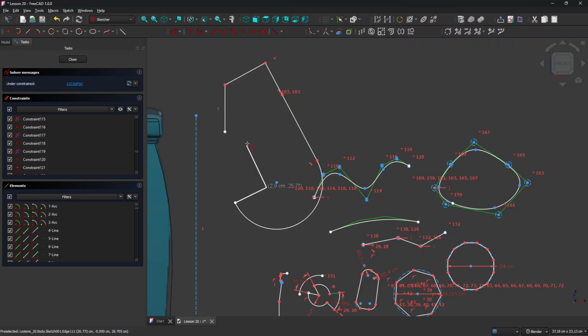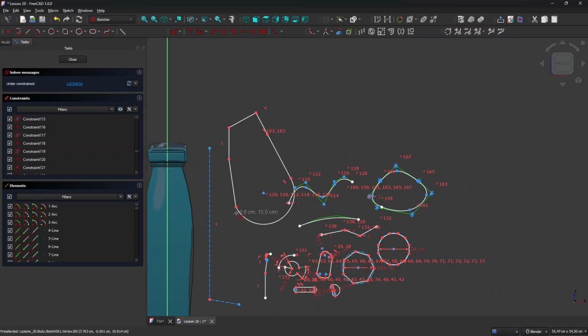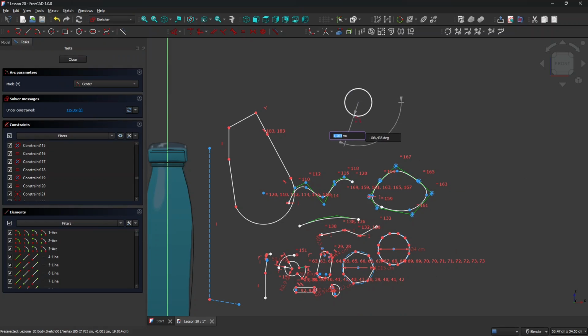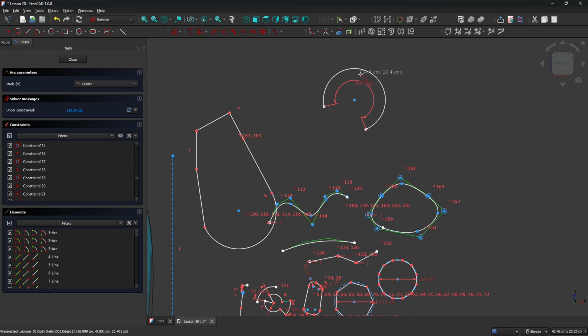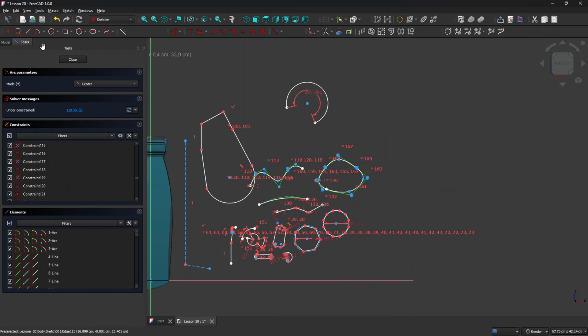Now M again, and M again if you want to go back to the polyline, and let's close this, and now it's a closed shape. So also with the polyline, you can create curved geometry. Next one is going to be the arc, and you have arc by center. So you create a center just like a circle, and then you define the arc. You can click with the left one. You can use the tab by typing the degrees. So if I say 100 degrees, it's going to be the opposite in this case, so 260 degrees around this circle shape.